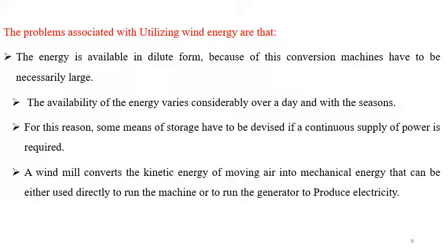The second type of noise is aerodynamic in nature, produced by the movement of turbine blades. One component of the latter is broadband noise, which ranges up to several kilohertz, and the other is a low frequency noise of 15 to 20 hertz. So that is one major problem.